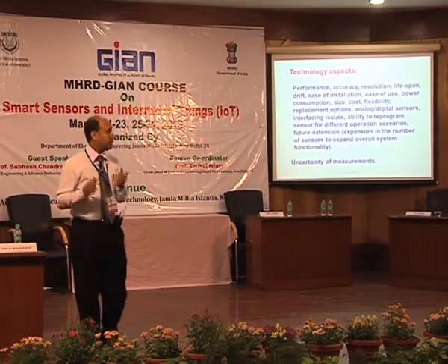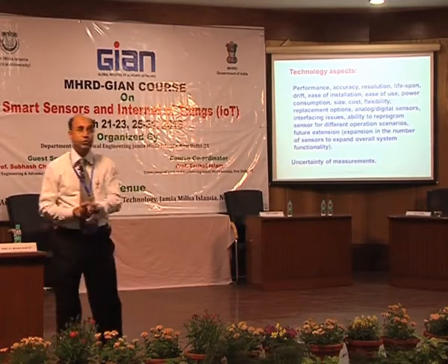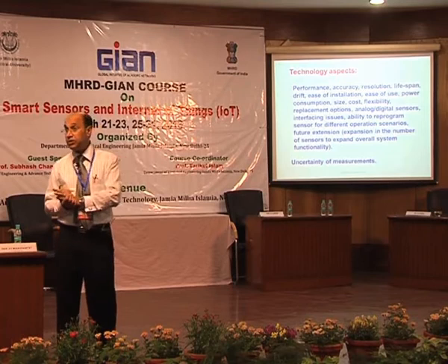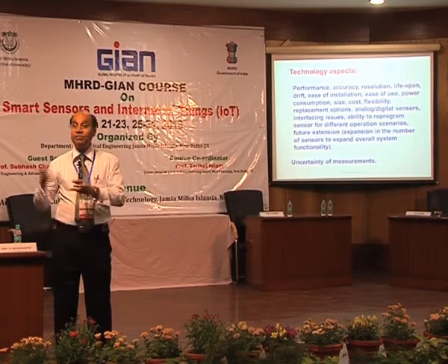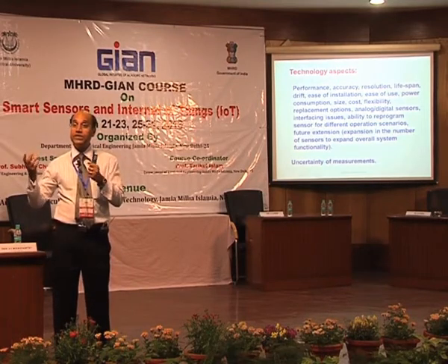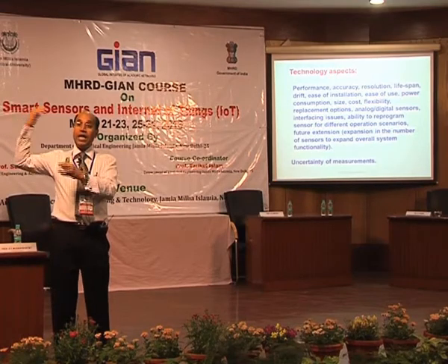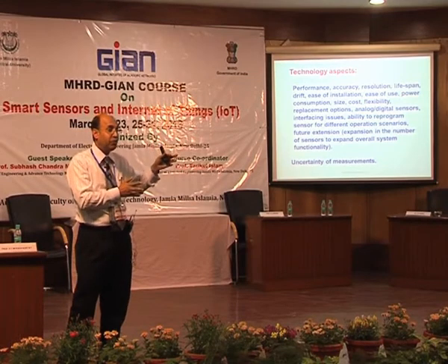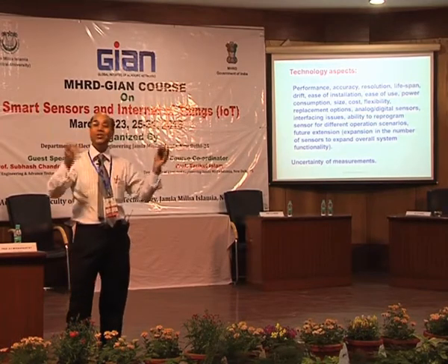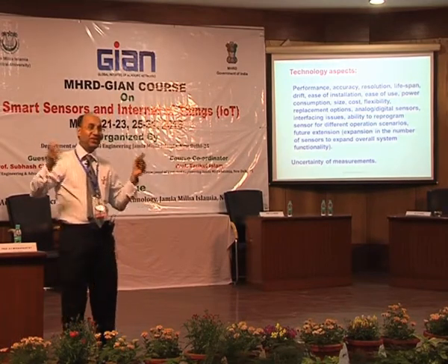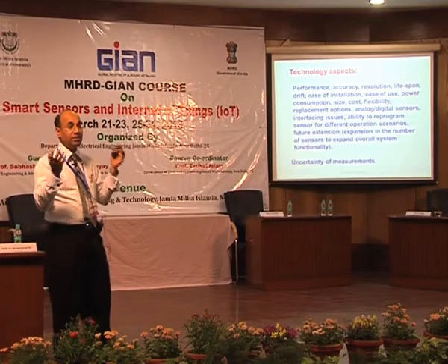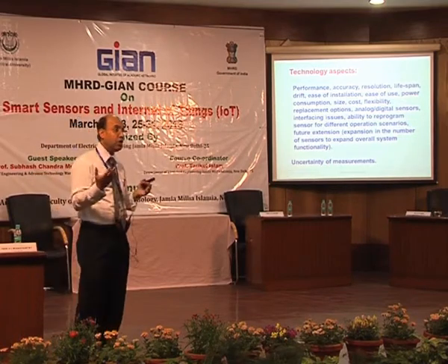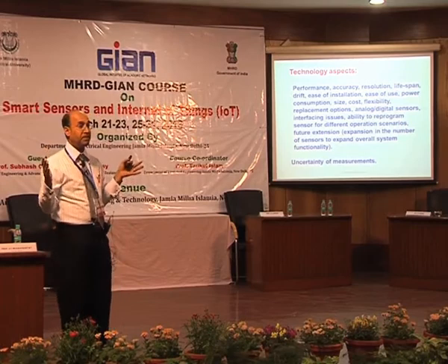I was talking with someone, a student, about structural health monitoring. The biggest problem of structural health monitoring is the lifespan. Lifespan of a structure may be 40 to 50 years, lifespan of a sensor is 4 to 5 years. Now, who will monitor whom? You see the practical problem. That is the biggest problem, if you do not have a long lifespan.